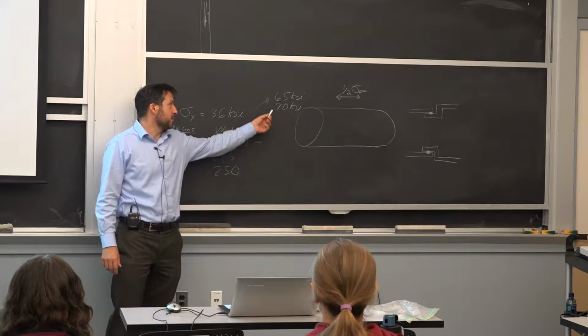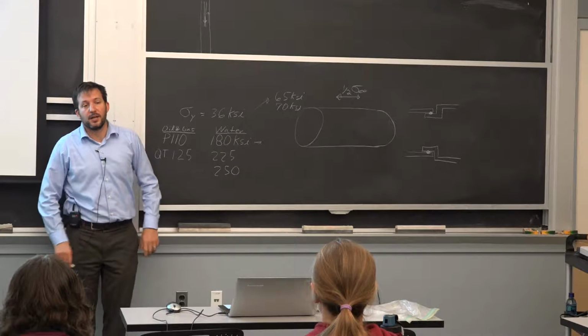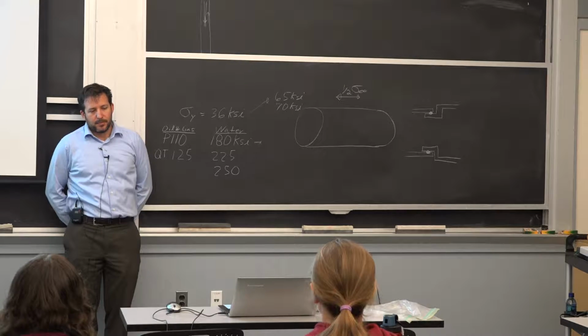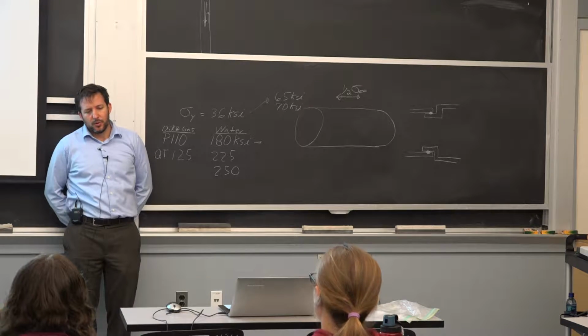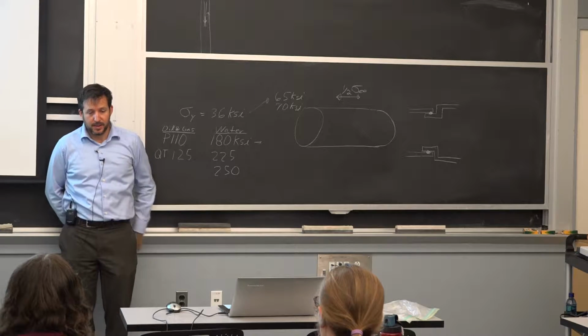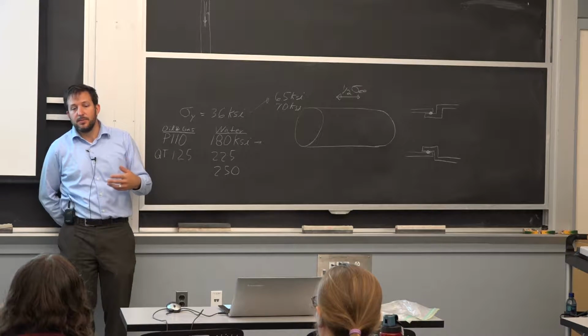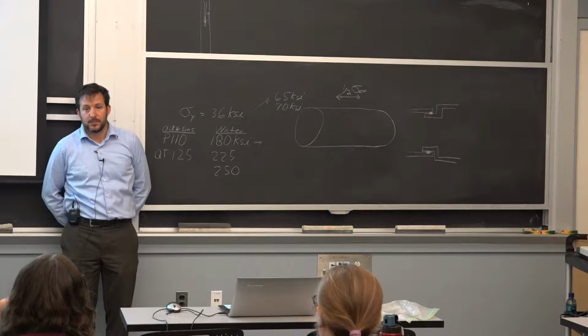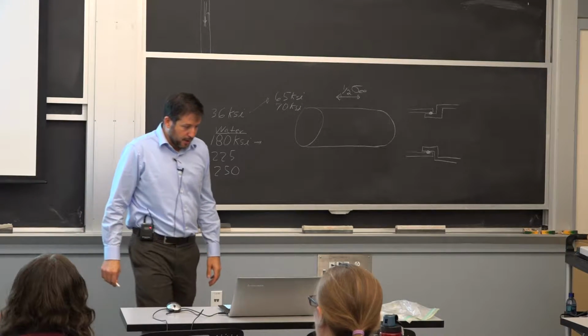But automotive in general doesn't use a lot of quench and tempered steel because everything gets welded. So think of it this way: every time you want a steel that is going to be welded, it needs to be a steel that doesn't get too hard during the heat treatment. That's pretty much the baseline.